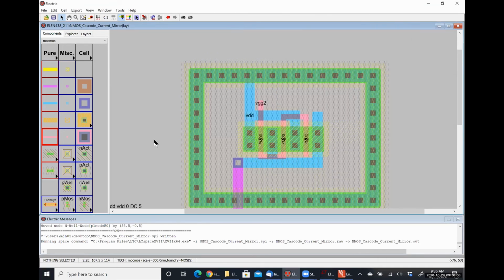Okay. I think the reason why it's not treating it as a long length transistor, if we had deleted these contact areas in the middle, to where we're forcing this bit to be like, if this is the source, then we're forcing this bit right here to be the drain. If we didn't have those, it would treat this serpentine pattern as a long length, I believe. But yeah, that appears to work. So sure, that floats your boat. Go for it.